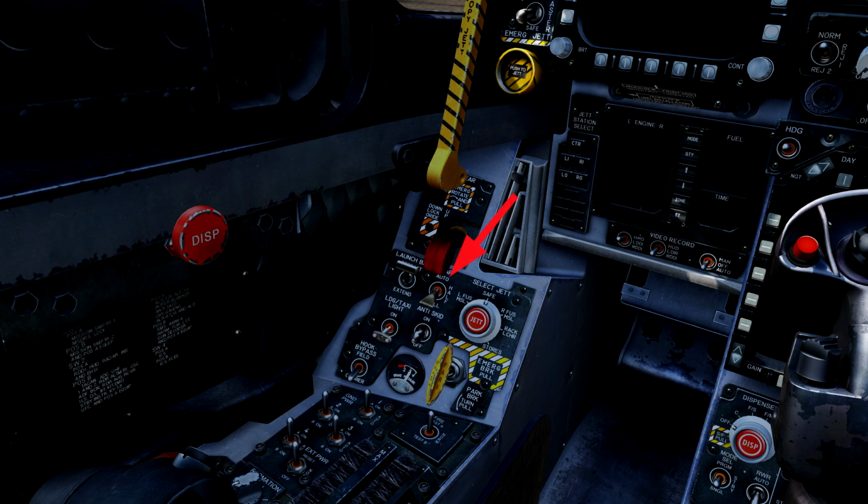And next to that we have the flap switch, which has positions for either auto, half, or full flaps. The anti-skid switch has a lock wheel protection circuit which will release the brake if the speed of one wheel is 40% of the other wheel. The landing and taxi light switch controls a combination landing taxi light that's located on the nose gear strut. And the launch bar switch controls the hydraulically operated launch bar that's used for catapult launches.